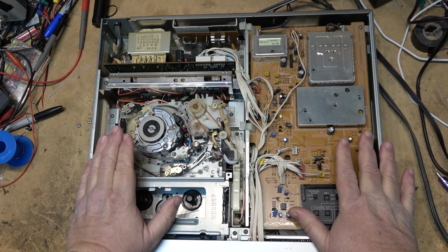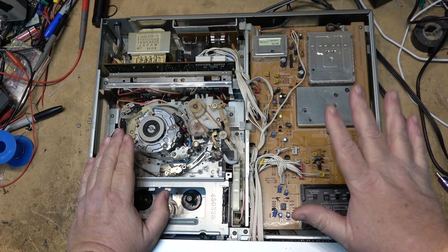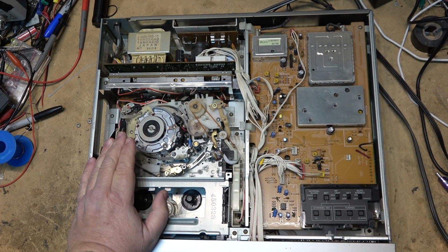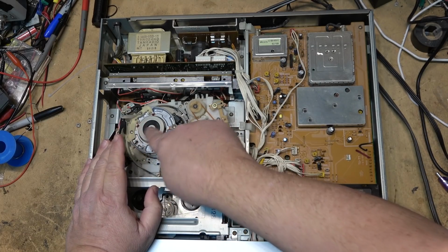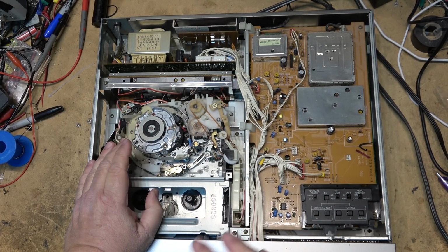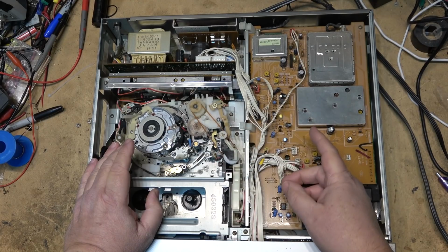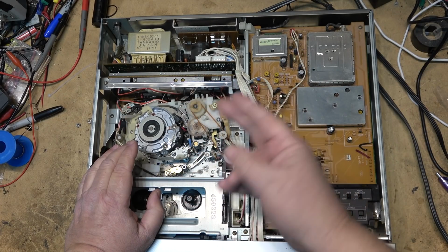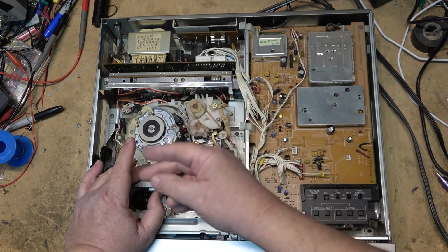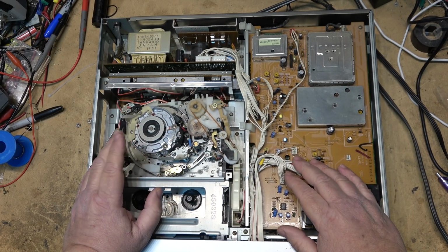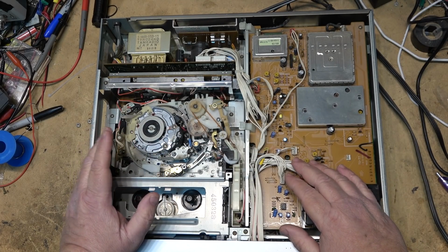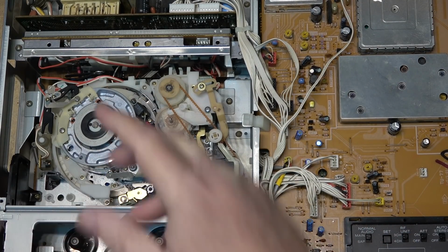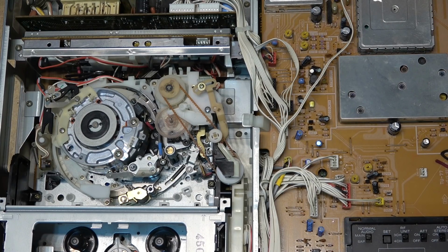They had the SLHF400, which is this one. They had the SLHF600, which was the next step up, and then they had the SLHF900. The difference between the 3 machines was this was a 2-head machine. The SLHF600 was a 3-head machine, so it could do slow motion and still frame, because it had a double azimuth head that had an A and a B field on it, and then of course the other head, which was just an A or B field, I think. Doesn't matter. Point is, it could play back the same field from both heads for still frame and for slow motion.